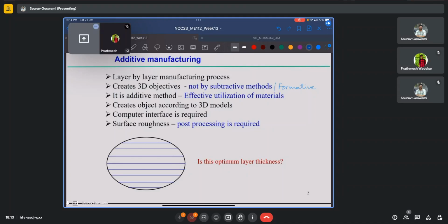It can process materials such as polymers, metals, ceramics, or even a combination of any or all of these in the form of multi-material or functionally graded materials. However, it is still limited by the layer height, which is not as fine as, say, that obtained in vat photopolymerization. So the choice of process will depend on the final requirements as well as the material which needs to be processed.